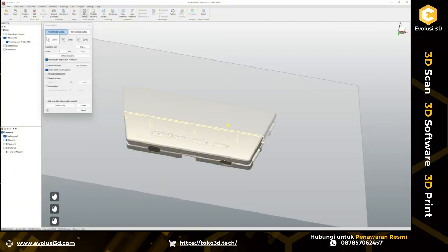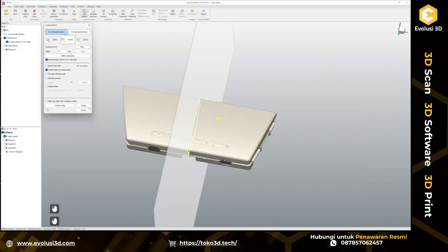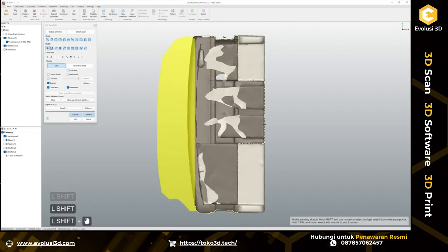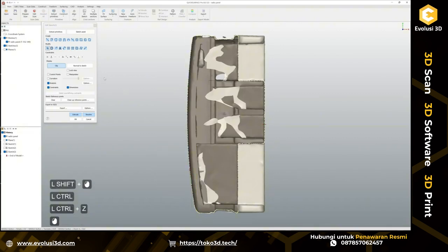So let's go and see if I actually can create this with just a simple extrusion. Let's try automatic fitting of entities. Okay, it gives me just a line. So let's go manually, arc, like this.